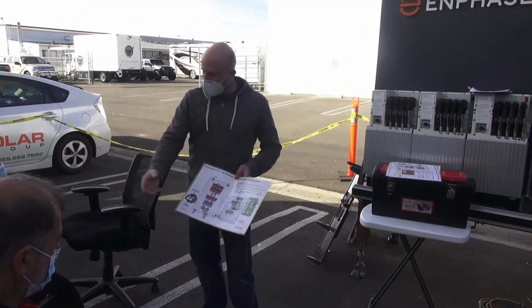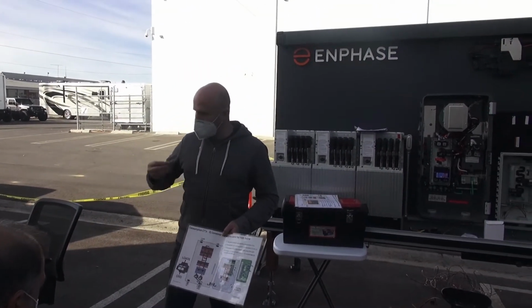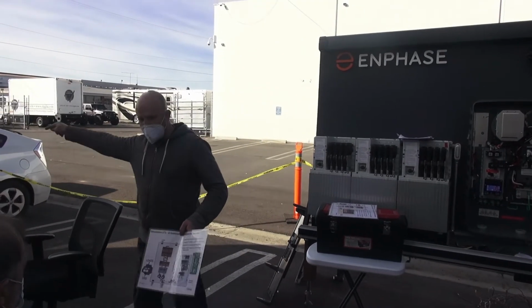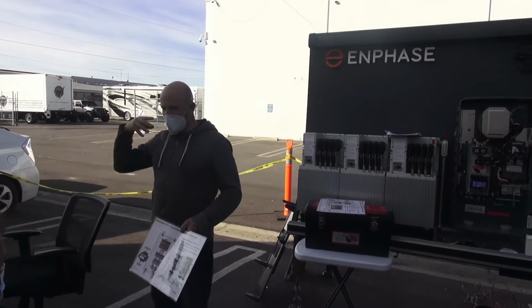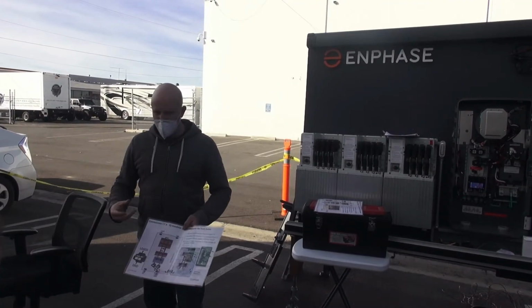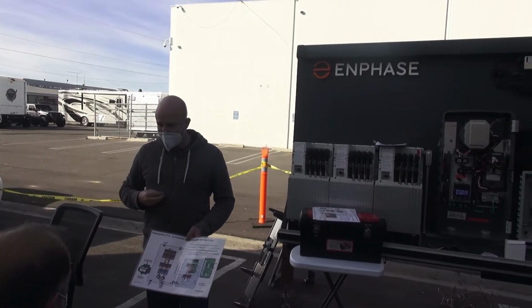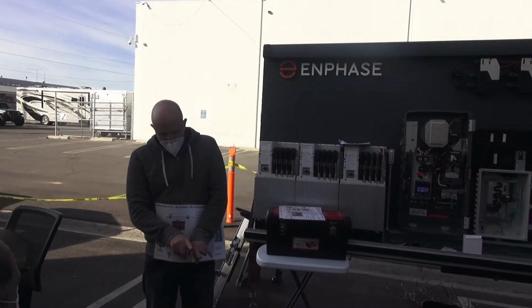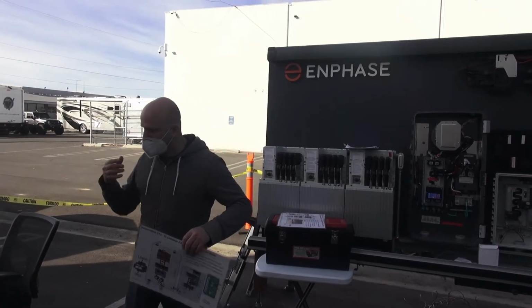You could try to add a set of CTs, but I'm telling you there's rational reasons from a design point of view where maybe you're not going to do $10,000 of trenching just to capture that one other load. I'm admitting that. But in general, I want to capture all of the power. And yes, you can use multiple sets of CTs, okay? You can have more than one black CT. You just double them up. Blue, blue, white, white. Together. It's almost like you have one bigger CT, okay?